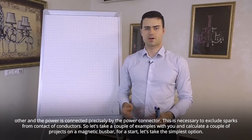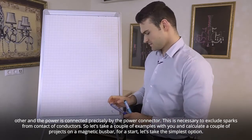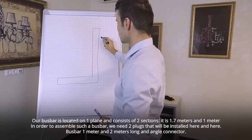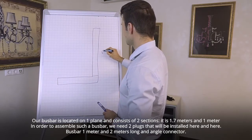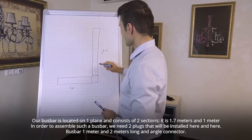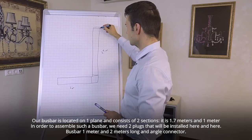So let's take a couple of examples with you and calculate a couple of projects on a magnetic busbar. For a start, let's take the simplest option. Our busbar is located on one plane and consists of two sections. It is 1.7 meters and 1 meter. In order to assemble such a busbar, we need two plugs that will be installed here and here.